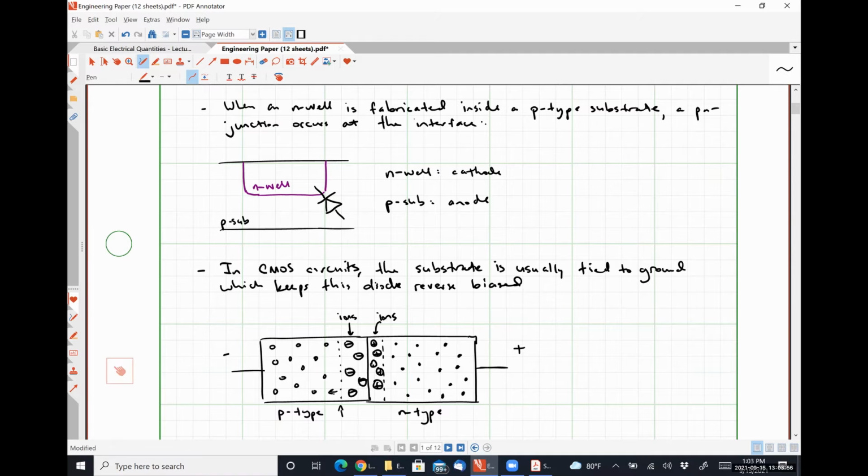That positive polarity terminal is going to attract electrons, which is going to move the boundary of that positive bound charge region to the right, overall causing the space charge layer to get wider, right? So there is more charge being uncovered, but the region of bound charge is now larger.